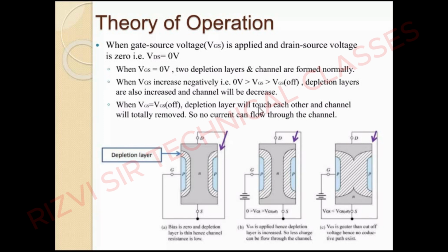In this condition, the depletion layers are touching each other, and the channel will be totally removed. The channel is totally removed, so no current can flow through the channel.